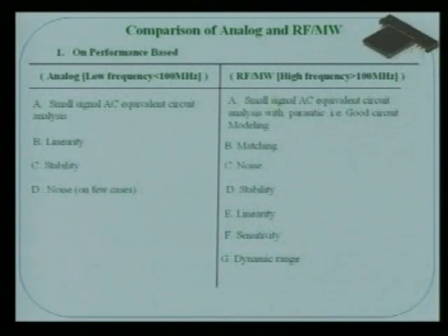Then noise, which is of paramount interest in circuit design, is how to interpret the noise. Basically, you first have to diagnose the sources of noise, and then solve it, that is, reduce the noise. Because you have to detect signals out of a noisy platform, and the signal to noise ratio should be high enough so that you can detect appreciable signals to get some information out of it.